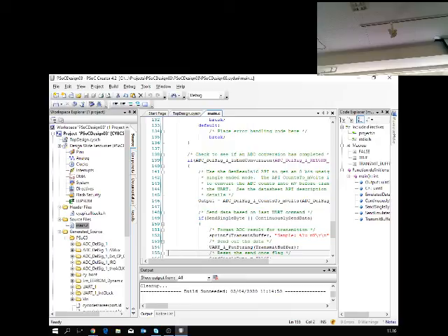Oh wow, it also has an interesting function that returns the millivolts. How many millivolts was the ADC result? You can use that one. That probably would be a nice way to go, since you know that your signal is some hundreds of millivolts. It makes it much easier to calculate the real temperature that way.